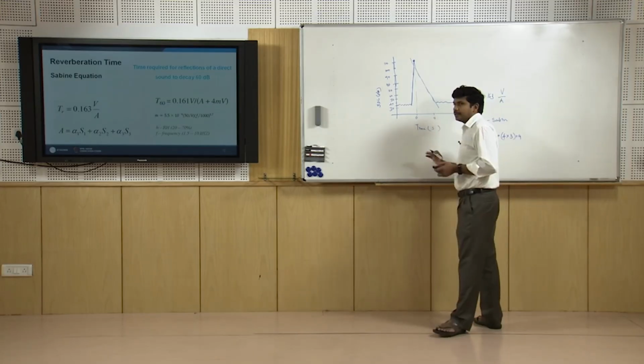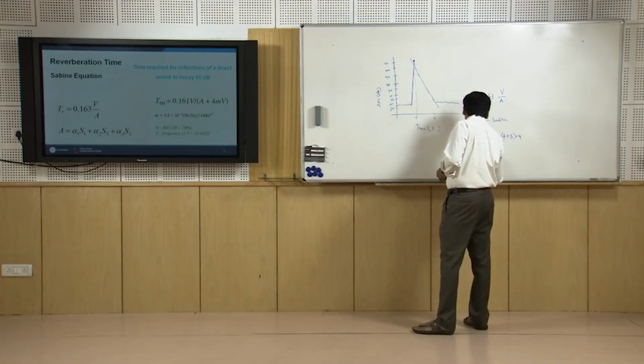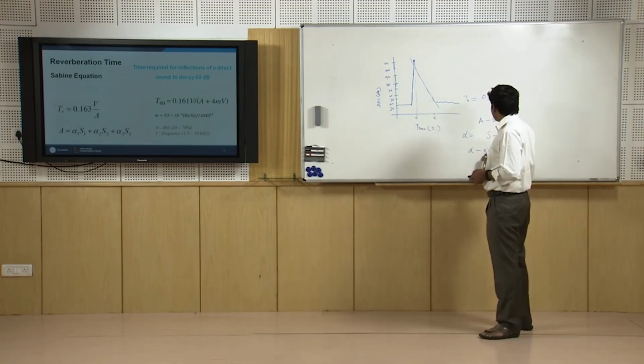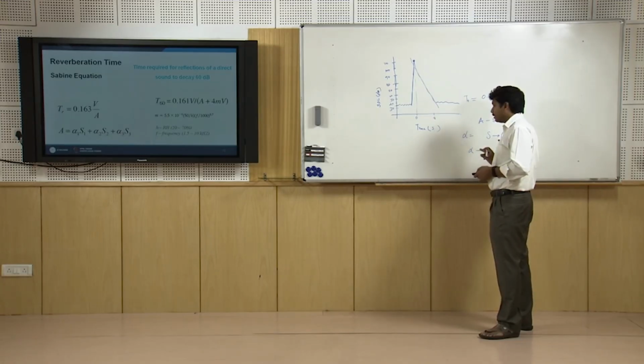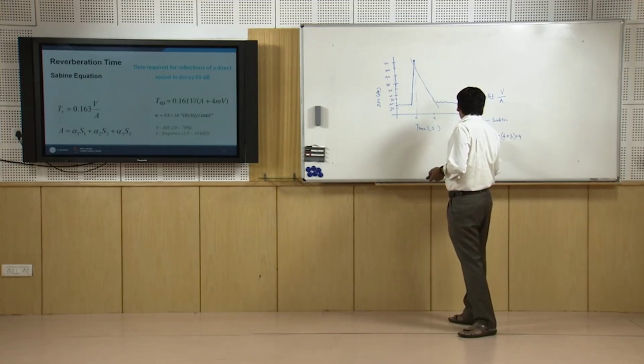The wall does not have any absorbing material surfaces. The absorption coefficient ranges from 0 to 1. 0 means it is perfectly absorbing, 1 is totally reflecting, it is a coefficient. Say for a typical untreated reflecting wall, the reflections probably will be around say 0.85 or 0.9.